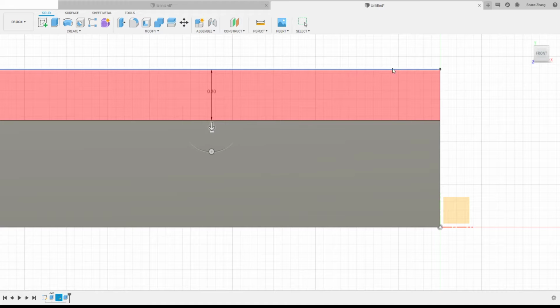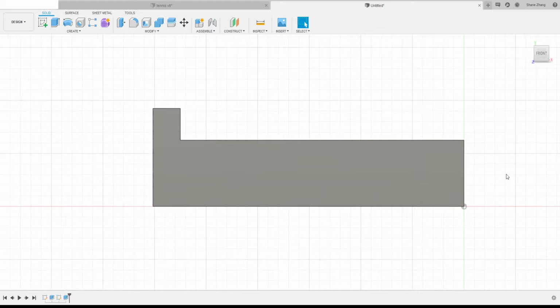So basically we extrude from the top, and we want to extrude to the bottom plane, but not all the way. So we have an offset value here. We're gonna set the distance. Alright, then we're gonna say okay. So right now this height here is 7/8 inch.